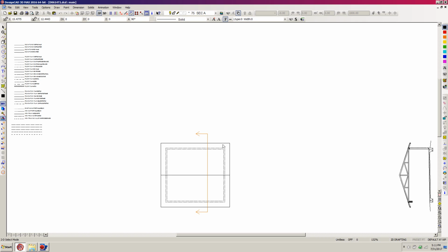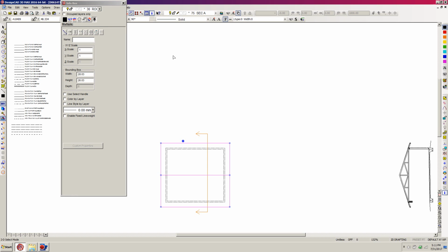I'm going to click OK, and the first thing I'm going to do is select the roof plan, which is clicking near the outside and then holding down Shift and clicking on the ridge also. And I'm going to activate the info box over here on the right hand side and click on that. And I'm going to duplicate these roof plan lines. So I'm going to hit N for duplicate and right click near that handle. Sets one right on top of the other, but they're both in layer 30 right now.